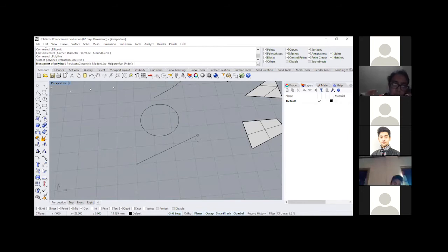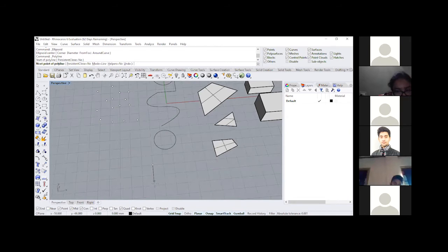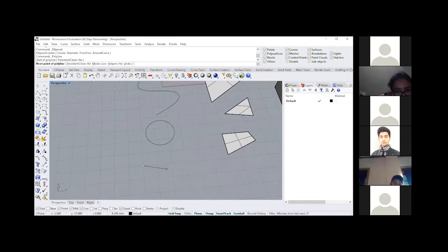Now you can see that it is not snapping to the ortho. It's not snapping to the x-axis or to the y-axis, right? If you wanted to snap to the x or y-axis while you're drafting, you can always hit shift. The moment you hit shift, it will snap to the orthogonal axis. So you can see how it is changing from either x or y.